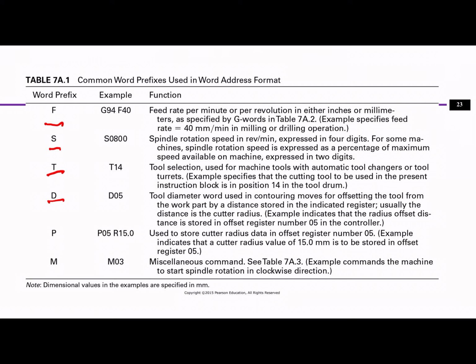When you are programming it, if you are telling the tool to move from one position to another, actually the whole tool is moving, right? So the whole diameter is moving in that direction. So when you are programming, you need to make an offset to make sure that the edge of that tool diameter actually machines the workpiece. This is how the offset works for a tool.